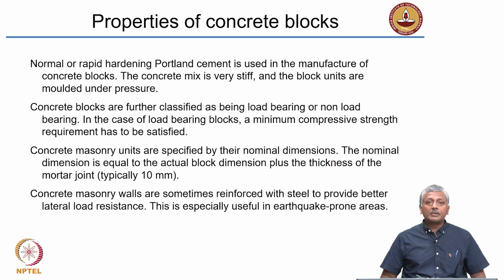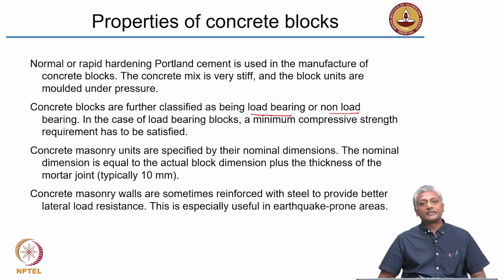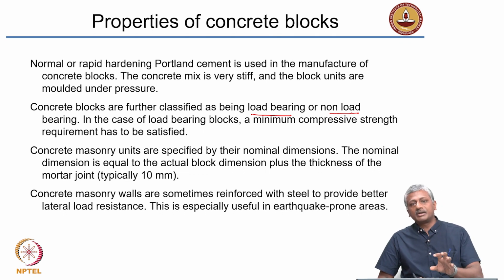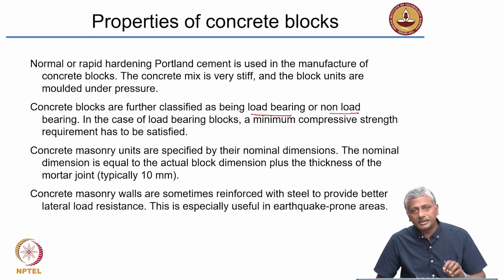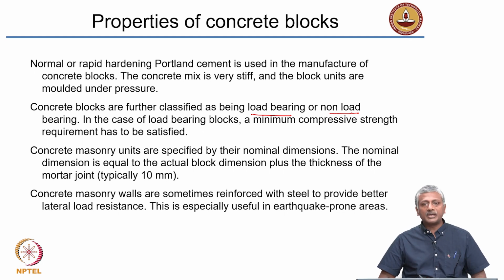Okay. So concrete blocks could be used for load bearing purposes or non-load bearing purposes. When they are used for load bearing purposes, obviously they need to satisfy a certain minimum compressive strength. I have not covered here the IS codes that deal with concrete. I have talked about stone and brick earlier, but with concrete I have not really covered this IS code for blocks here, but you can have some idea about this from reading the content in IS codes. So you need to have some minimum compressive strength to satisfy the requirement for load bearing masonry.